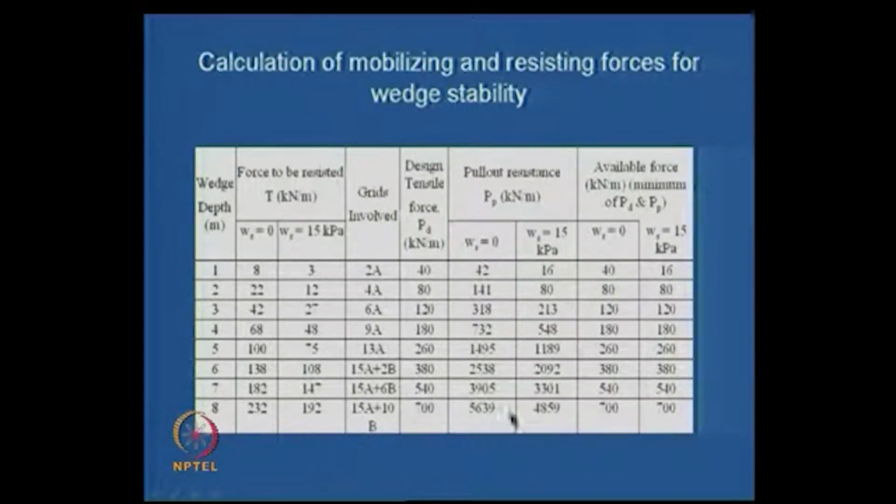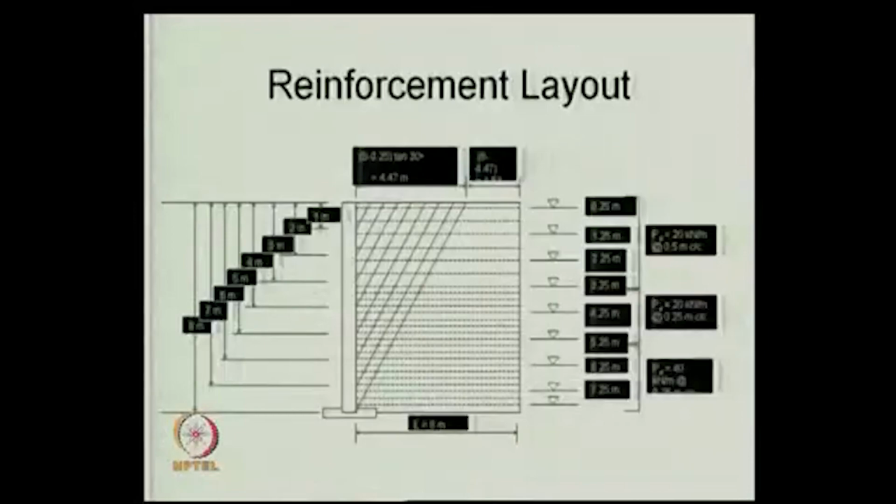So essentially one needs to formulate a sort of evaluation like this, and in fact there are many software available to calculate. If you just do this, this is the way that it should be provided, like 1 meter, 2 meters and all that, and design spacing should be 0.25, it should start here, and then you can have spacing, and L is the length of reinforcement.